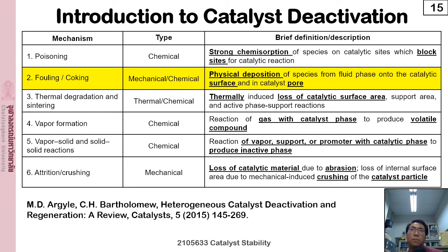This pressure will make the catalyst break and collapse, and the breaking of the catalyst particles will result in the formation of powder. As the large catalyst particle becomes powder, it will block the reactor during operations. So it starts as a chemical deactivation, propagating to mechanical deactivation, and it completely deactivates the process.